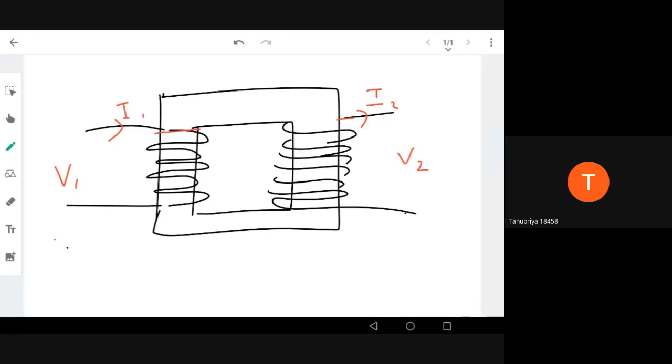Okay. Then I have to postulate a structure. So I have to model the transformer using some circuit elements. We have input voltage and current. So definitely the circuit elements will include resistance, which blocks the current. There will be capacitors, there will be inductors, etc. In a transformer, definitely there is a lot of winding, so there will be inductors at the input and output. So we try to model the transformer using these elements, which we call lumped parameters.